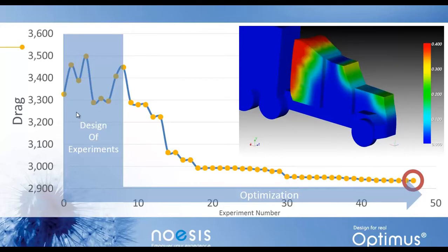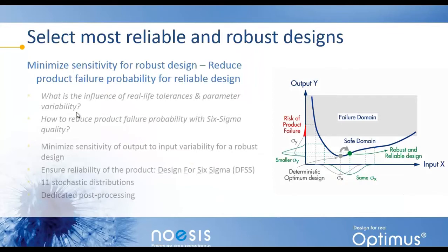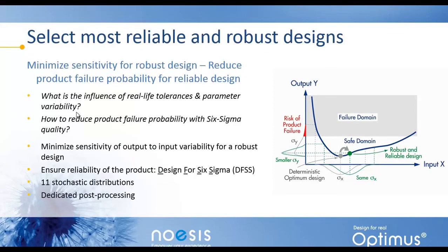At the high end of optimization, we have many of our automotive and aerospace users, for example, who use Optimus for robust design. Robust design is taking the optimization process a bit further. In this case, you have variability associated with those input parameters. For instance, you may have a build tolerance. As a result of that variability, you're also going to get variability on your output.